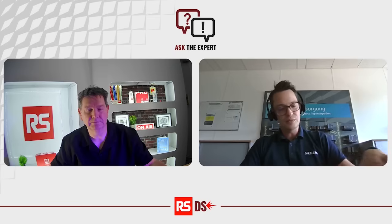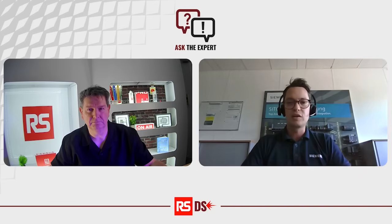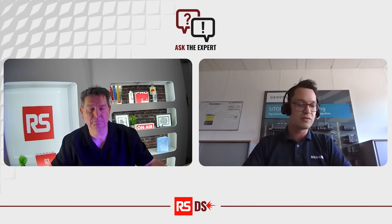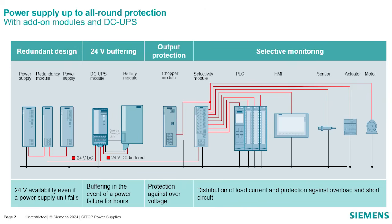There are many things you have to consider because it's not only about the power supply itself. You can also have a really reliable electrical cabinet by ensuring that you have some plan B, I would say, in the event of a failure from the power grid. Here you can take, for example, a buffer module, which can buffer or bridge the event of a failure from milliseconds to seconds. It depends on the load you have to take out of the power supply. And the other thing is you can also go up to hours if you use batteries, for example.